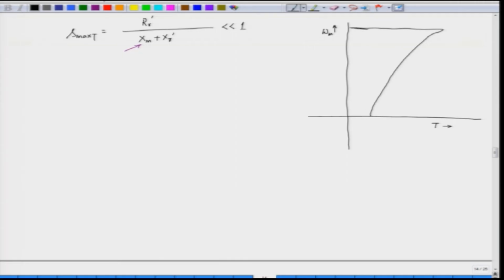And if we go on varying this current, we get a family of curves like this. So, this is for IS1 current, this is for IS2 and this is for IS3, and this of course is the synchronous speed which is omega ms, the origin, and we have the torque speed characteristic, and this slip for which we get the rated torque is very, very small. So, this is the operating slip.